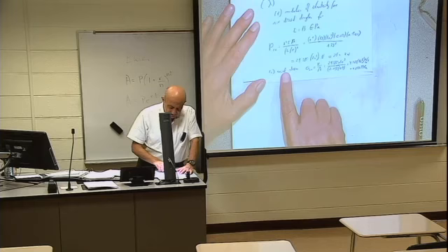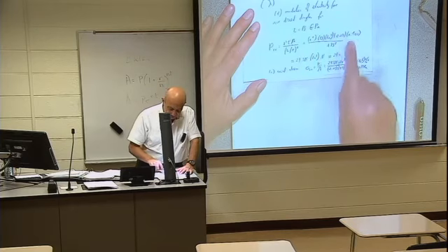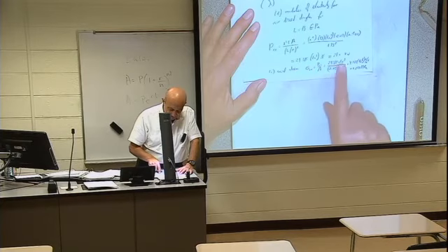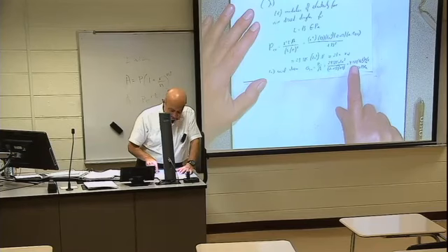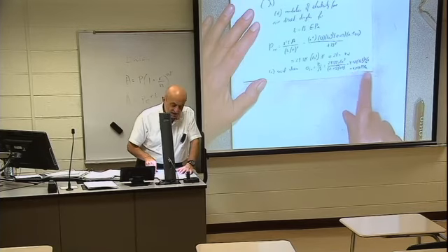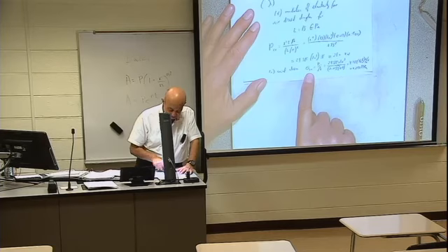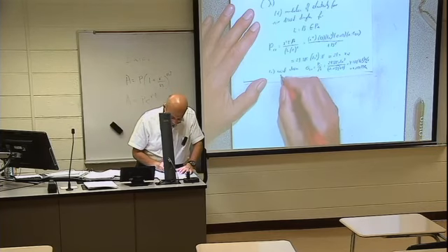Okay, axial stress. Sigma critical equals P critical divided by A. So 21.385 times 10 to the power 3 newtons divided by 0.05 times 0.1, that is an area, equals 4.277 times 10 to the power 6 newtons per meter squared, or 4.277 megapascals. That is the stress at buckling.